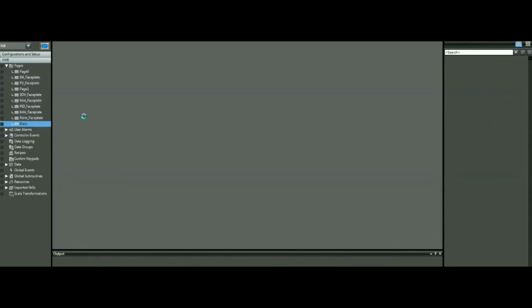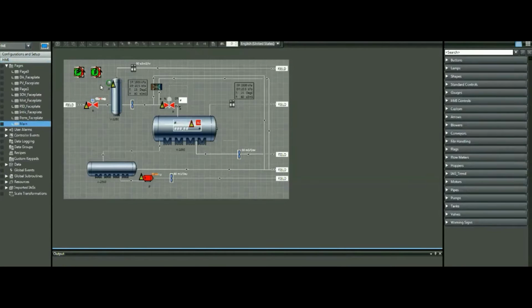When it comes to the process interlock and the process permissive, if we take the motor faceplate as an example, the interlocks and the permissive are already included in that object.